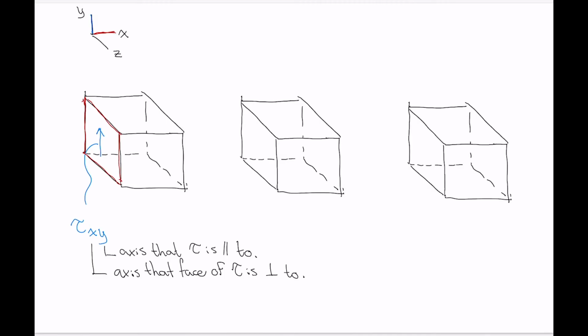We talked about the idea of complementary shear stresses and how if we have one shear stress here for static equilibrium, we need to have another shear stress on this side pointing downwards, but now that element still isn't static, so we need to have that complementary pair of shear stresses, one on the top and one on the bottom, pointing in that direction. So those shear stresses all have to be the same as one another, and when you have one of them, then you know you have the three others, so they need to exist in a set of four like that.